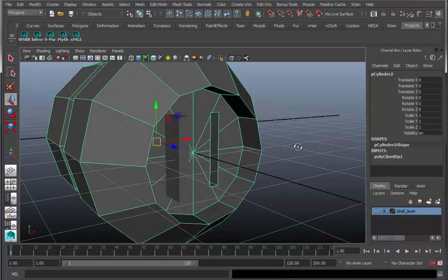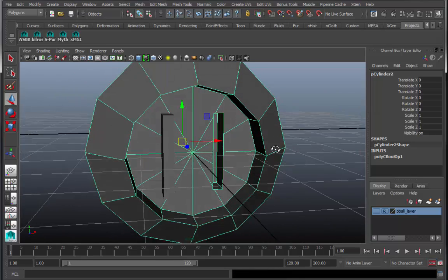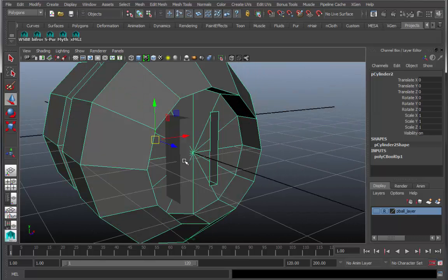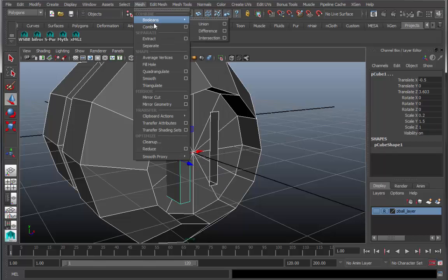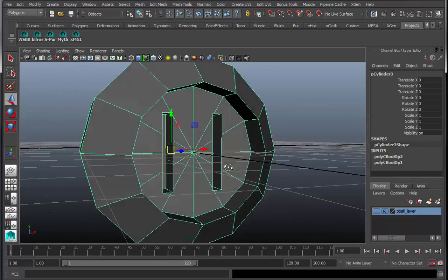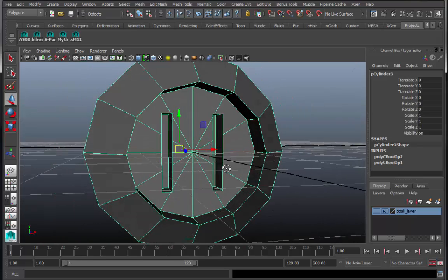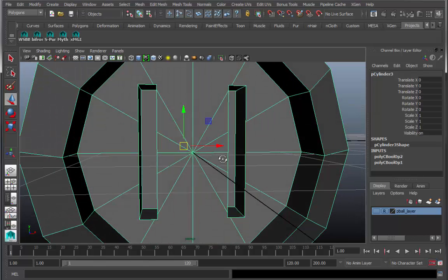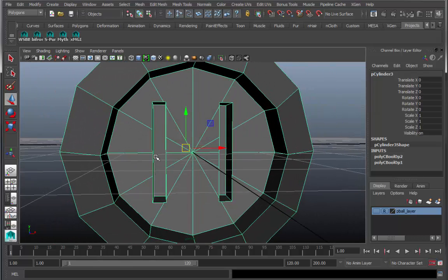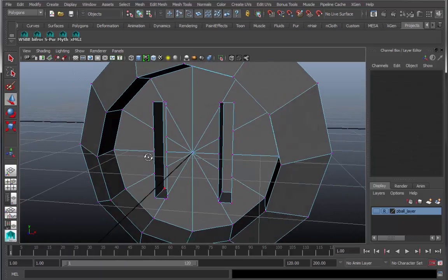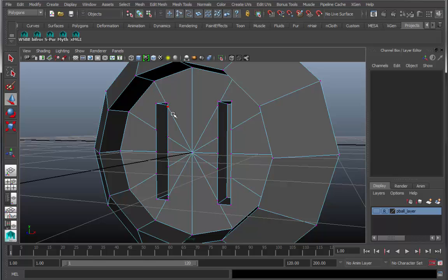So now you see that it's dug out a hole, but more importantly, it has the interior geometry of that hole. And you do the same operation for the second one. And now we have a doorknob electrical outlet. Wonderful. So we need to resolve some issues here, which is that the Boolean operation has created dozens of little tiny vertices here.